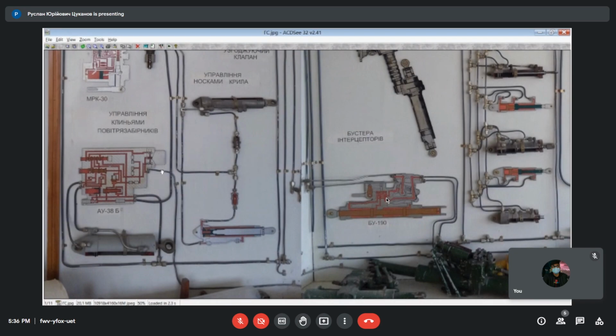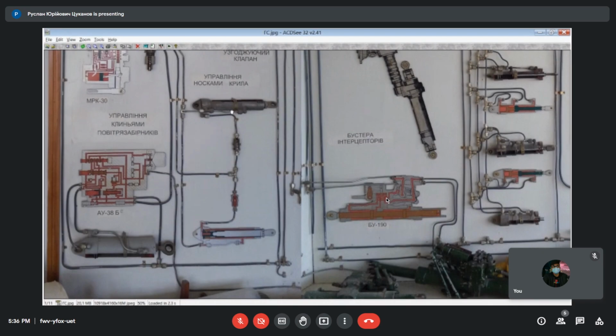It's the control of the air intake, also shown as one unit. In your book, it will be the extreme left cone in the bottom, so air intake control, and one hydraulic cylinder actuator for air intakes. A feature of this airplane is that it has two air intakes arranged side by side to the fuselage, and it allows the use of one actuator and rather simple mechanisms, rods and bell cranks, and it's enough to control both air intakes. So that is a feature of its arrangement.